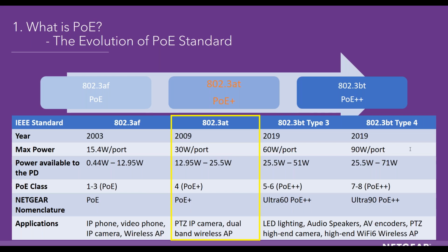Okay, so what do you foresee as the future trend of PoE? I think it heavily depends on the evolution of the powered devices. In these slides you can see that the evolution of the PoE standards goes from 15.4 watts maximum to 30 watts per port maximum, then to 60 watts and 90 watts. It's all because there are powered device applications that require such high PoE.